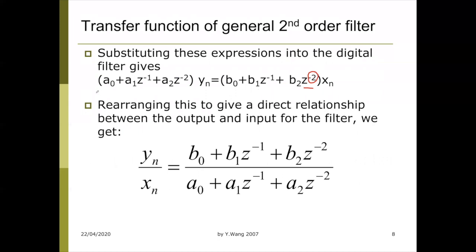So hence you can convert the difference equation into this so-called Z transform. The beauty of this mathematical tool is that it eliminates any explicit past input and output samples. The eventual form of this equation no longer involves any past samples, because you need only y[n], which represents the current output, and x[n], the current input. Everything else has been encoded. The time element of this filter has been encoded into this mystery Z factor.